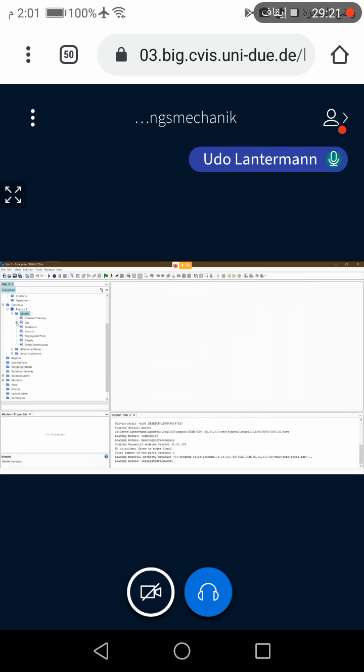Okay, now we check. We have chosen gas, and we want to simulate airflow. And if you open this gas phase, you will see air is the default one which is chosen from Star-CCM+ automatically if a gas as a fluid model is chosen. So we don't have to change it now. In our case, we want to simulate airflow, and that's chosen now. If you check the material properties, the density of air is given as 1.18 kilogram per meter cubed.